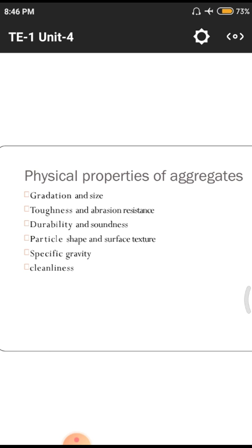After the 40 to 50 rotations are over, due to the impact of those steel balls, the material breaks. So we need to sieve after the breaking is over. Initially, what particle size we have taken, and after the test is over, what particle size we obtain. According to those particle sizes, we give the abrasion resistance to the aggregates.